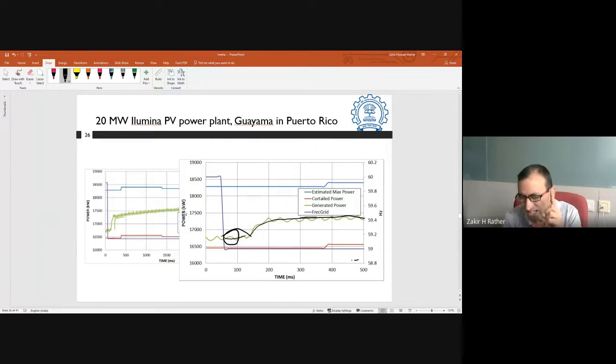It is not exactly the same instantaneous response from these inverter based sources when compared with the synchronous response. What I said is that in synchronous generators, the inertia starts instantly. Here, even though it is very fast, there is still a delay of 50 to 100 milliseconds in particular grid following converters. Grid following converters are relatively faster, yet they cannot be considered as an identical response to that of the synchronous inertia.